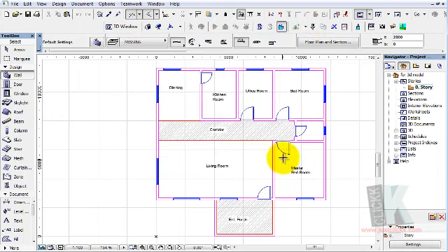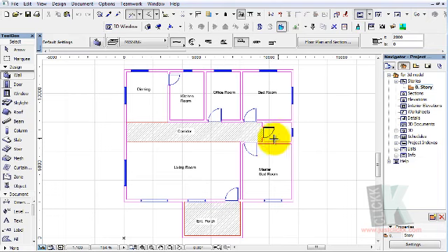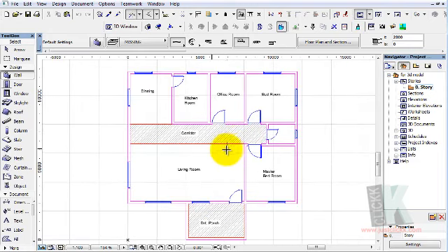Okay, so this is how you bring your drawings into ArchiCAD. Whatever drawing, you can just prepare it in AutoCAD and save it, and then you come to ArchiCAD and ask ArchiCAD to open the drawing, not import. Open the drawing. So ArchiCAD will ask you those certain things, and just follow up, and you're done. And you get to this place. This is all. So this is how you transfer drawings into ArchiCAD for 3D modeling.